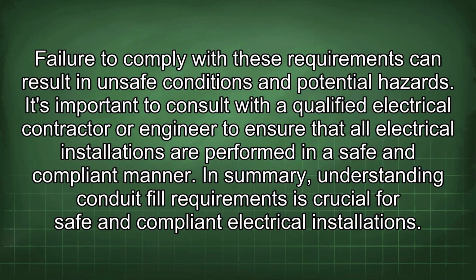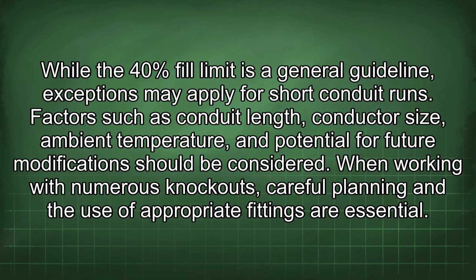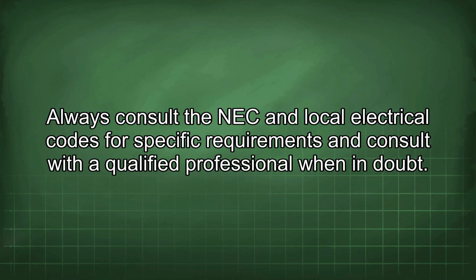In summary, understanding conduit fill requirements is crucial for safe and compliant electrical installations. While the 40% fill limit is a general guideline, exceptions may apply for short conduit runs. Factors such as conduit length, conductor size, ambient temperature, and potential for future modification should be considered. When working with numerous knockouts, careful planning and the use of appropriate fittings are essential. Always consult the NEC and local electrical codes for specific requirements and consult with a qualified professional when in doubt.